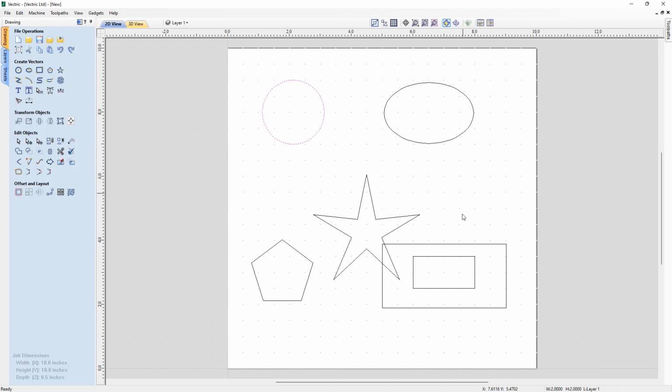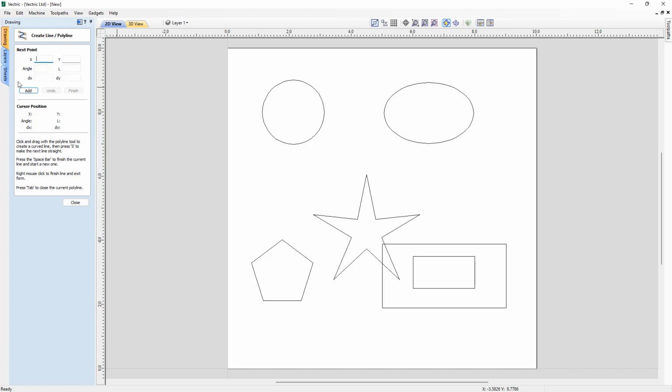So we're just going to switch off the snap grid. An easy way for us to do this is at the top view bar here. We have the option here to toggle off our snap grid. So click that goes on, click it, that goes off. Right then, so let's just go back into our Polyline tool. Okay, so you can see here I'm able to snap to the center of our objects, and you'll see a dot comes up there. We've got a target, so you can see how the cursor changes according to the item that we're actually snapping to.